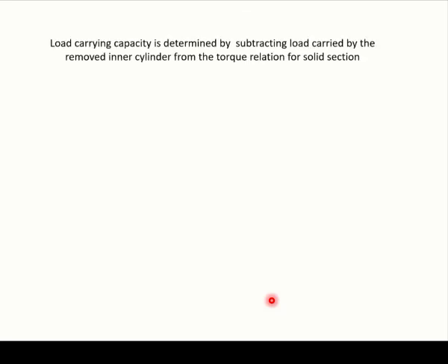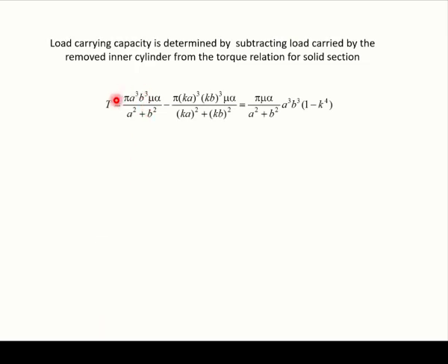And for the torque, now I know my value. So if you use the outer, so when x is equal to a, so it's elliptical with a and b. Okay, and now since I kind of cut the inside elliptical, I will just say that it's minus phi times, now my dimensions are Ka and Kb. So if you do that, this is what you will end up with. So this is my torque for this hollow cross section.